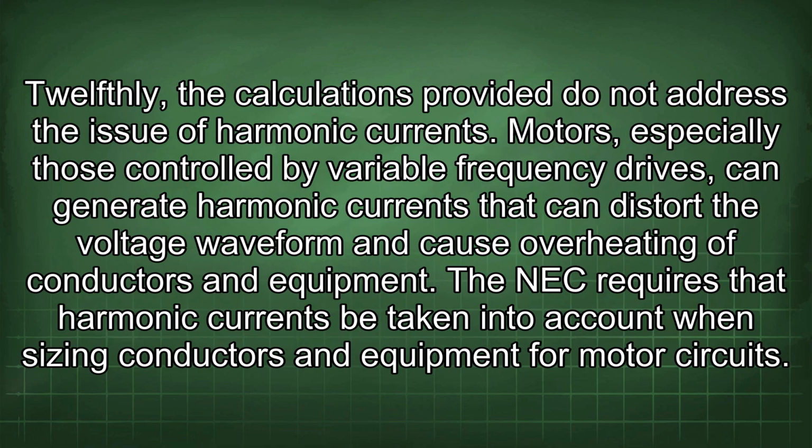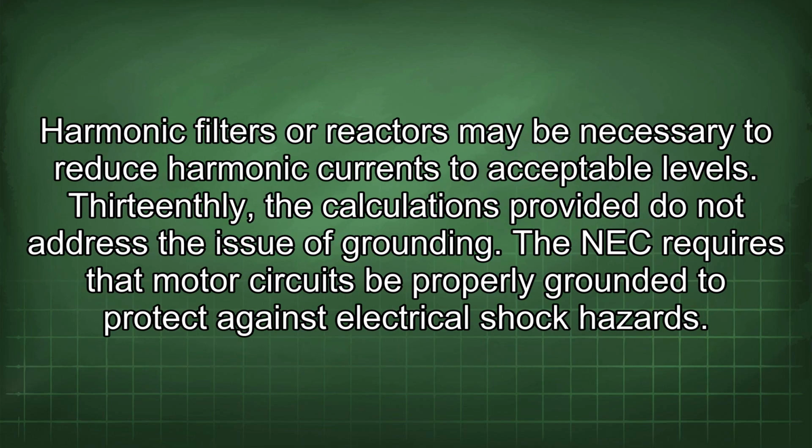12thly, the calculations provided do not address the issue of harmonic currents. Motors, especially those controlled by variable frequency drives, can generate harmonic currents that can distort the voltage waveform and cause overheating of conductors and equipment. The NEC requires that harmonic currents be taken into account when sizing conductors and equipment for motor circuits. Harmonic filters or reactors may be necessary to reduce harmonic currents to acceptable levels.